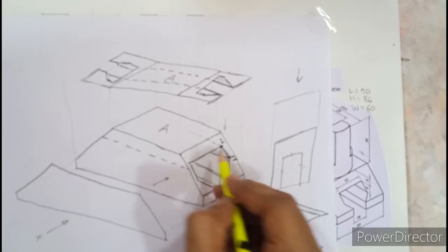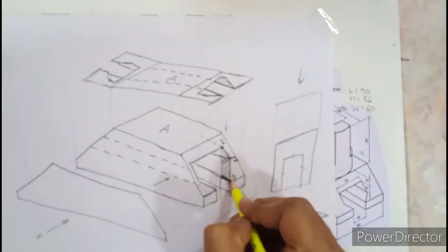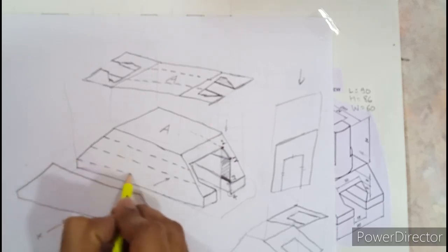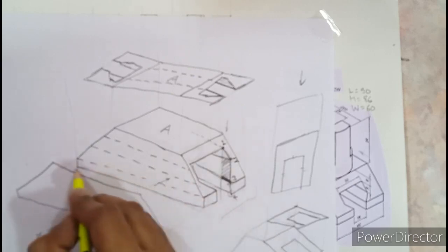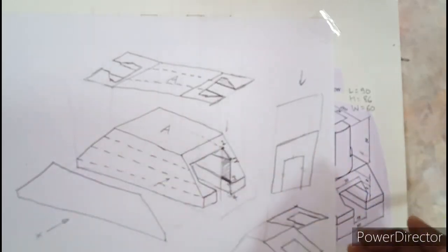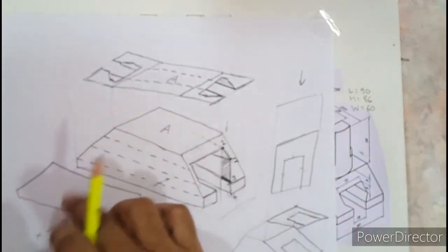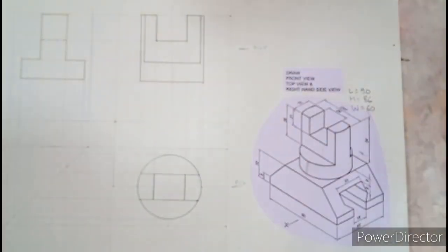Similarly, from edge number 2 you cannot see the edge passing inside. So this is the hidden line for edge number 2. Edge number 3 is in line with this another edge. So here you'll find the third edge as hidden. And last, this fourth one overlaps with the basic bottom edge. So these are the various views you can see from the front and top. I have shown you this because we need to reflect the same drawing while preparing this diagram.